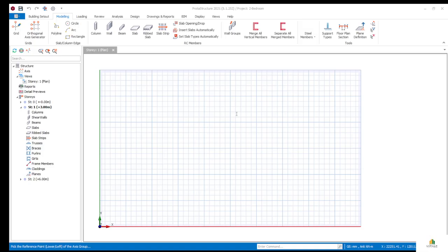So now I want us to choose these dimensions, then we work on them. First we will choose 4,500, then comma, then we will choose 3,000, then comma, then we will choose 1,000, comma. So if the spacing between the axes are not the same, are unequal, you use comma to separate the values, and it's supposed to be in millimeters, please, right?